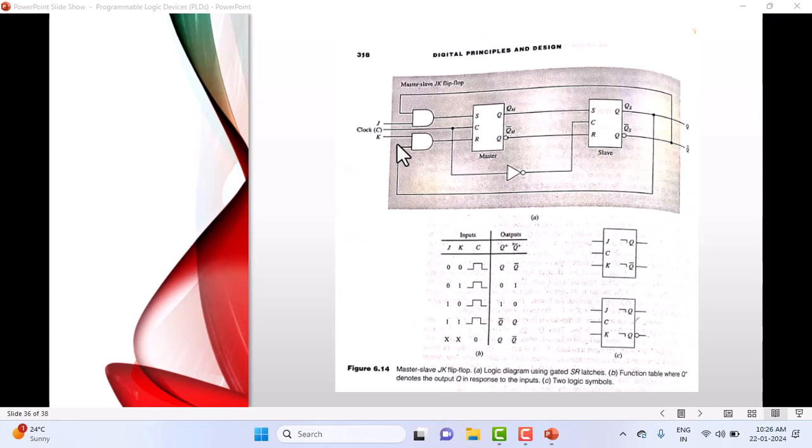Understand? My view is that I look at logic design from a different perspective. Whenever the computation part comes in the logic design, I use a combinational circuit. And when the computation is over, I store the result in the memory. Are you getting what I'm trying to say? Suppose I ask you to develop some square root or logarithmic kind of circuit, you will do some computation in that, right? After computation, you are supposed to store the data. Otherwise, what happens? You lose data.